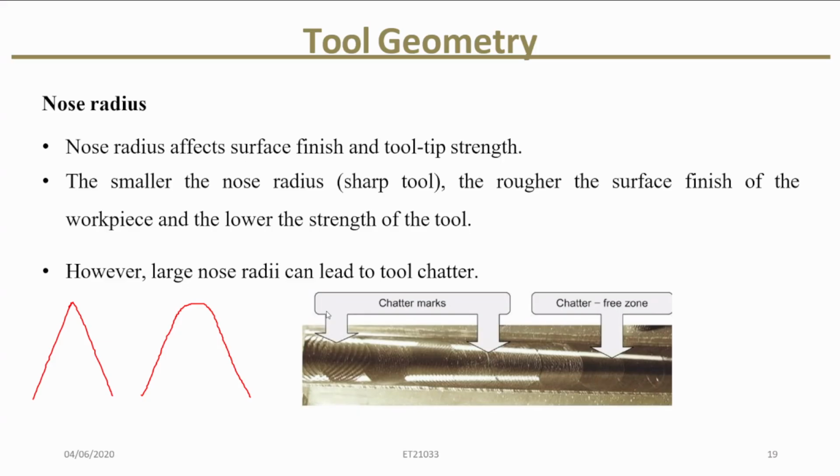When we consider the nose radius, it is a trade-off of finish versus stability. The bigger radius means a stronger corner and smoother finish, but there can be chatter on light setups because it raises radial force. The smaller radius cuts lightly and is good for fine features, but it leaves a rougher surface and is weaker.